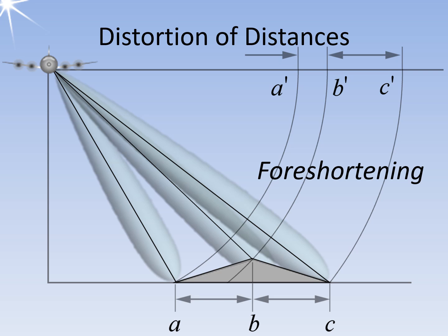However, on land, presenting single measured values in a clear and interpretable manner can be challenging due to the often significant variations in heights. When measuring in a slant range, side-looking radar receives echoes from higher terrain elevations before it receives echoes from objects located at lower elevations. As a result, the distances measured in the radar image are not represented in actual proportions, leading to distortion caused by so-called foreshortening. For instance, consider a mountain slope that tilts towards the radar.